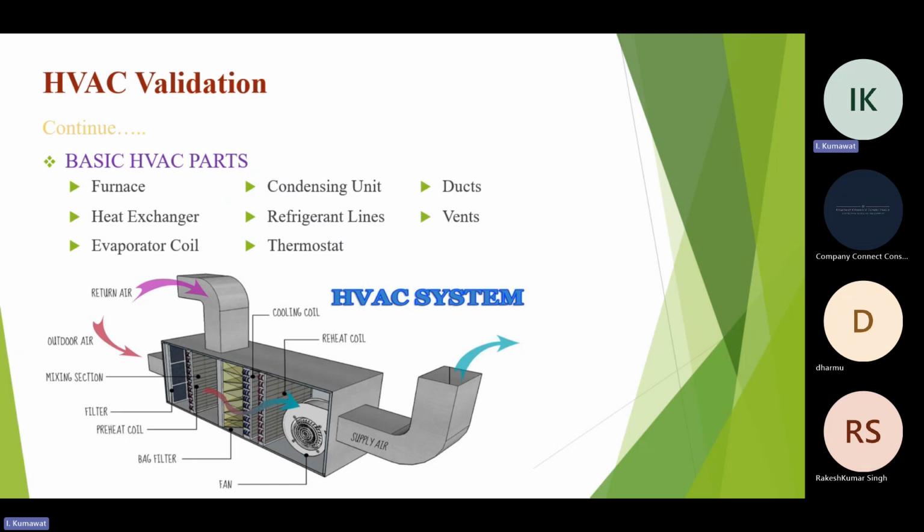In that case, different makes and models are available in the market, and that equipment contains filters like the HEPA filter, fine filter, and pre-filter. Three types of filters are available: first the 10 micron filter, another the 5 micron filter, and third the HEPA filter, which is the 0.3 micron filter. Each of the filters will be qualified during the qualification activity, and further we should have a schedule to verify the integrity of that particular filter.